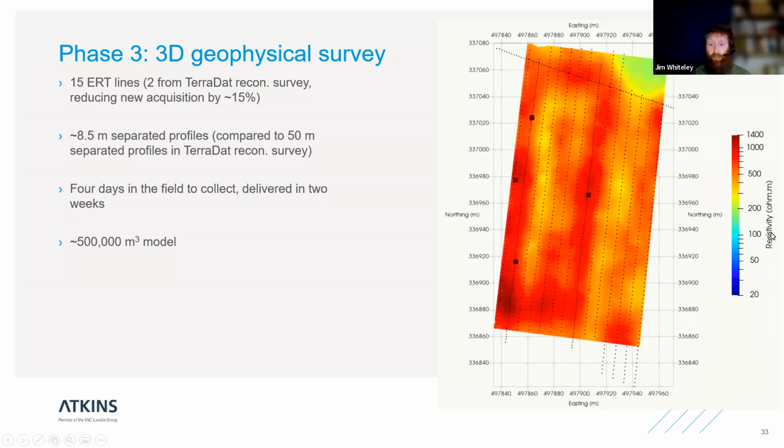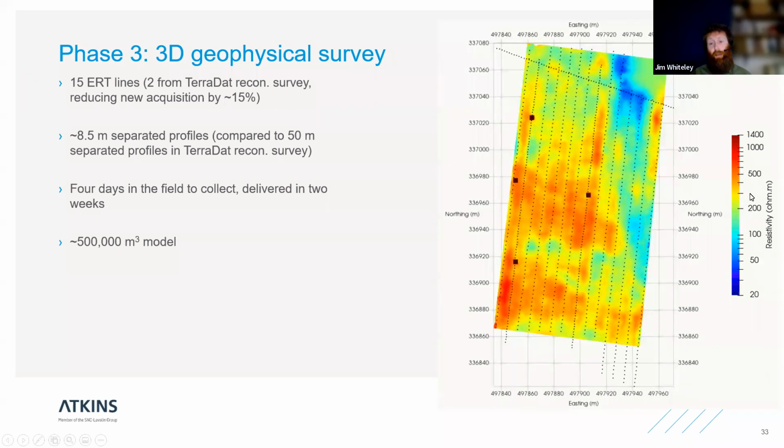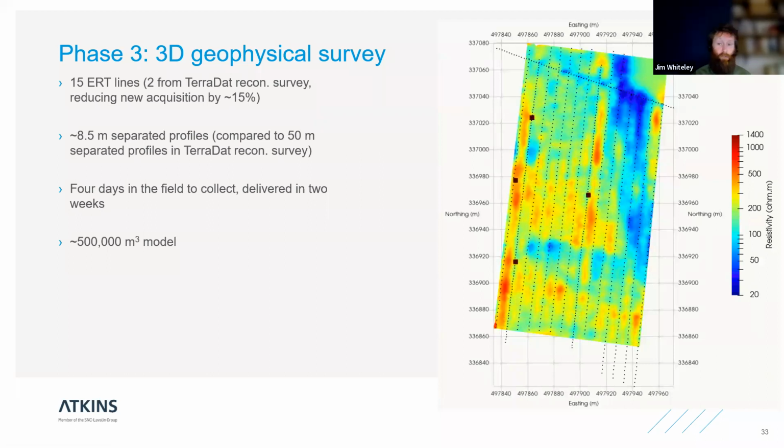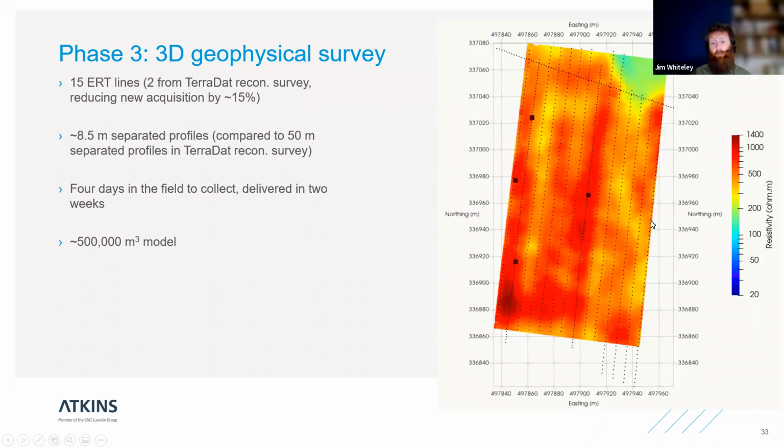And actually, if you look at this area in between those boreholes, we've got these yellow and orange values here, which is pretty low resistivities for the site, and that means that there is some change in the ground character there. As we get to the surface, we can see this dark blue we think is the influence of seepage from that pond, which was water filled, possibly flowing through an existing channel or having just found a preferential pathway in the near surface, and that's great.